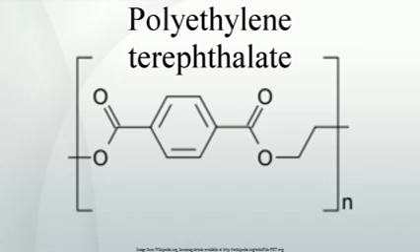Hydroxide and peroxide groups build up at the surface of the products made of polyester in presence of air, oxygen, and humidity. This process is accelerated by ultraviolet light. During an ulterior treatment process, hydroperoxides are a source of oxygen radicals, which are a source of oxidative degradation. Destruction of hydroperoxides is to happen before the first thermal treatment or during plasticization and can be supported by suitable